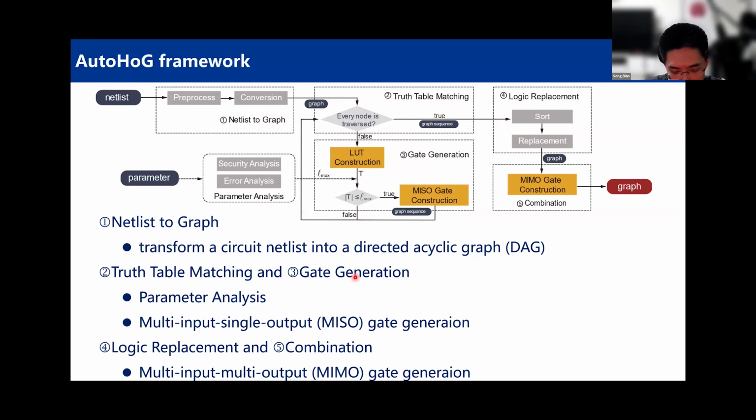So basically, we start to look at regions of circuits to see if these gates can be merged together to form a compound gate. The method is that we encounter a node and explore its neighborhood using graph algorithms, and try to generate a homomorphic FHE gate that can perform the functionality of that particular region.